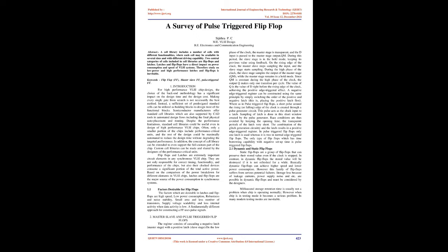2.1 Dynamic and static flip-flops. Static flip-flops are a group of flip-flops that can preserve their stored value even if the clock is stopped. In contrast, in dynamic flip-flops the stored value will be destroyed if it is not refreshed for a while. Basically, dynamic flip-flops can achieve higher speed and lower power consumption. However, this family of flip-flops suffers from serious potential failures. Storage loss because of leakage currents, power supply noise, etc. are possible in dynamic flip-flops and must be considered by the designers.